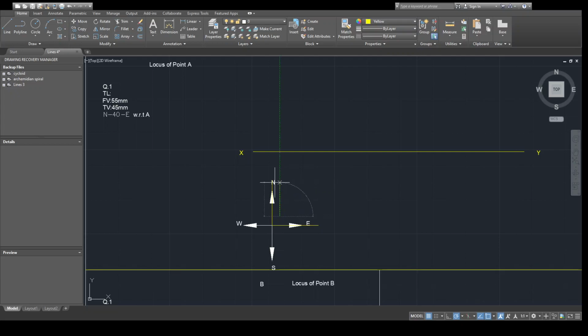So what will we do? If you draw this line from this point, it shows an inclination from east to north of 38, 26 like that, but we need to draw it from north to east 40. Obviously the north-east angle is 90 degrees, so from north to east 40 means east to north 50 degrees, because 90 minus 40 comes to 50.